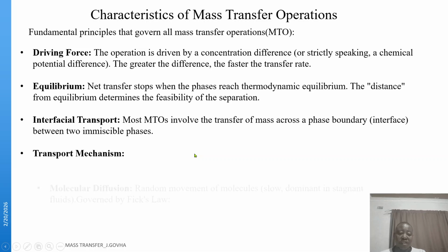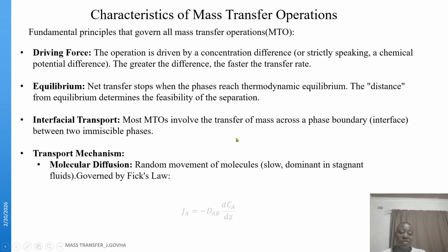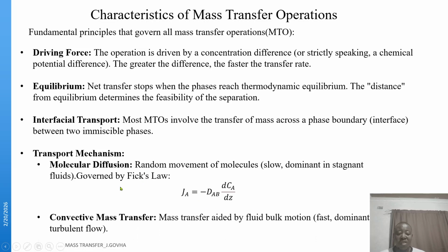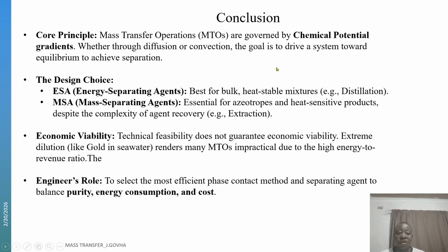Then transport mechanism, molecular diffusion, is governed by Fick's law indicated as an equation there. And we also look at convective transfer, where transfer is due to bulk fluid motion. So basically, the core concept here is